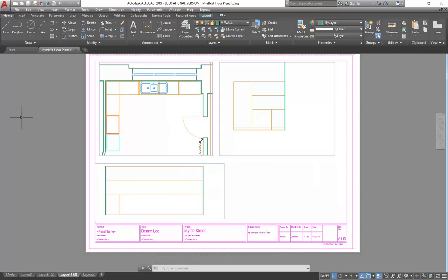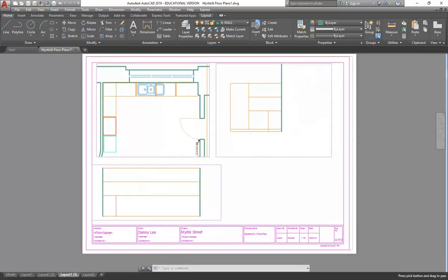So that's it. And yes, that should give you a good setup for all of your joinery drawings. You can use exactly the same approach for your bathroom elevations as well. If I was setting this out, I would do it like that. Like I was saying, go clockwise if you can, and then you can have sections. You probably need 2 sections for these joinery units, and they could go down here or to the right of this one. You've got room, and you're going to have notes and things, so they'll take up the rest of the page. But that should do it.